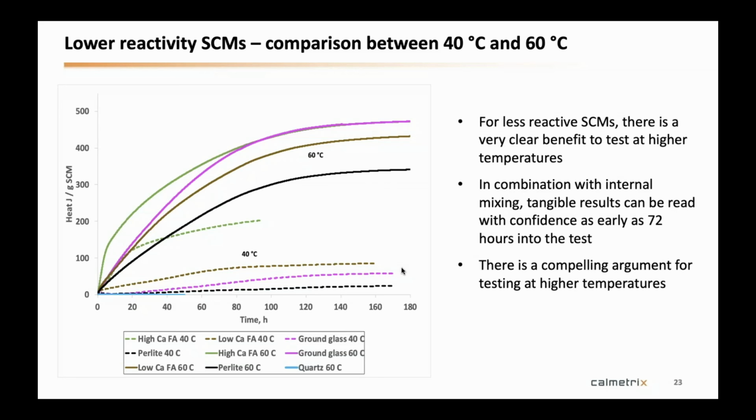If you want to do external mixing, the ideal situation is you want no temperature gradient at all. So you want to limit it to the minimum. It's not really a recommendation. It's just the closer you can get to your actual temperature that you have in the calorimeter, the less effect you will have. And what I mean by less effect is the signal will stabilize quicker.